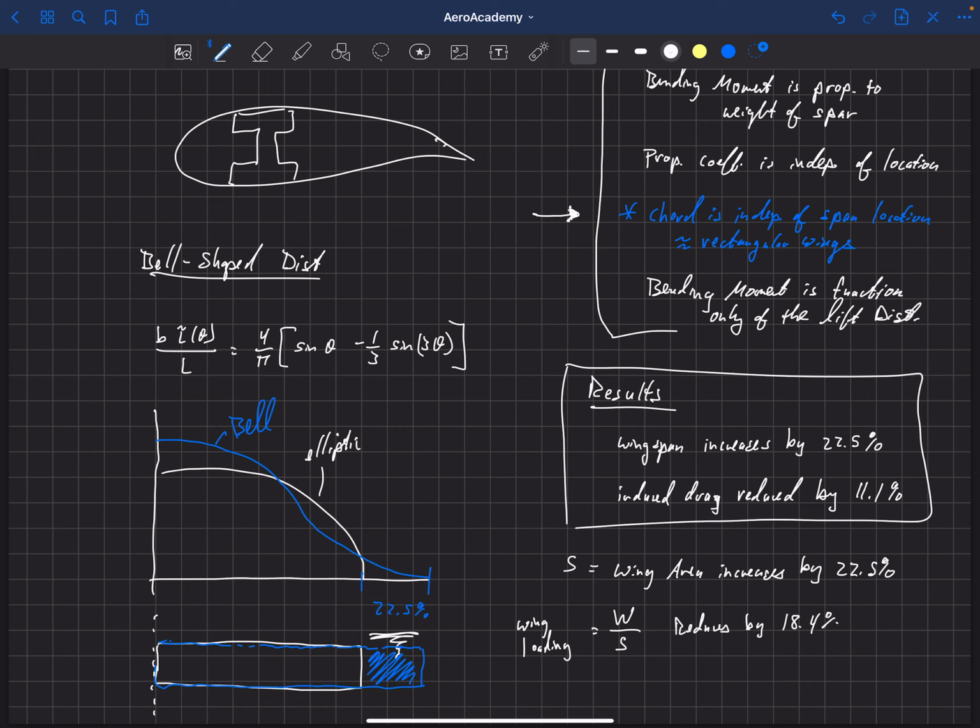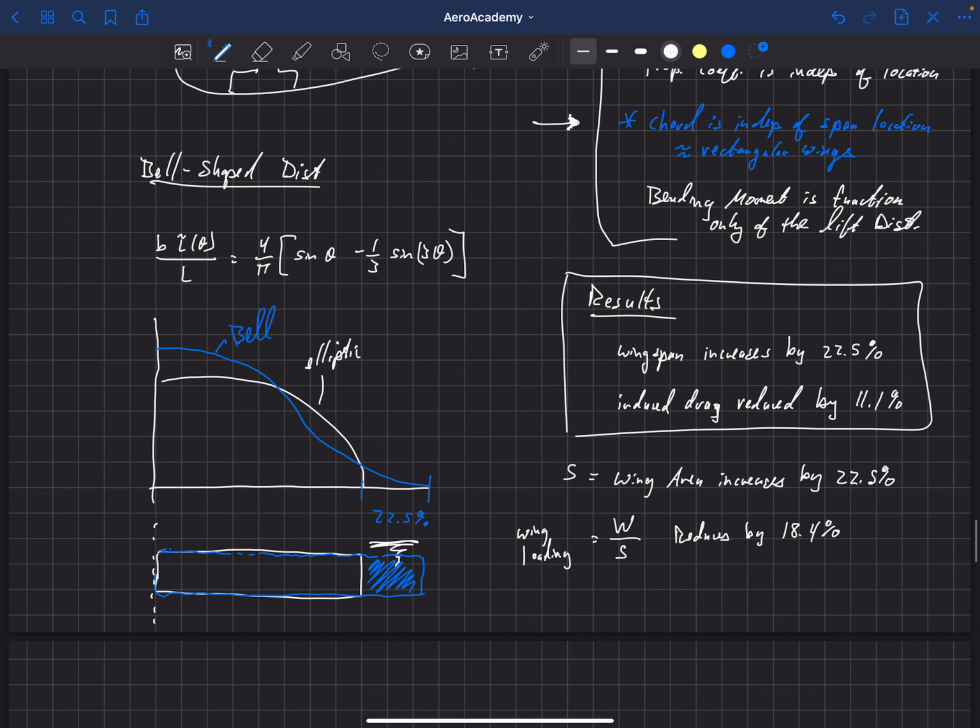Okay, so why does that matter? Well, because the wing loading is related to our design speeds. Most of our design speeds, minimum power, minimum thrust, and even stall speed, are directly proportional to the square root of the wing loading. So this term shows up in our design speeds.